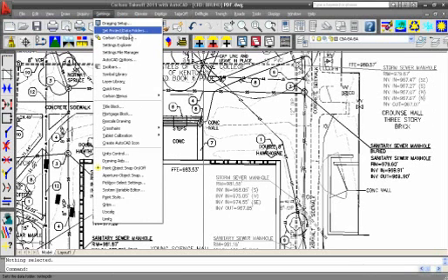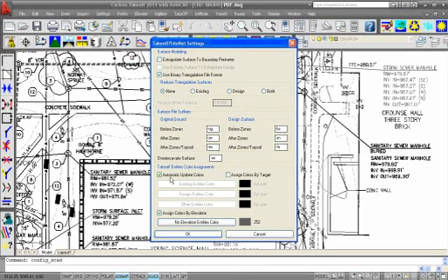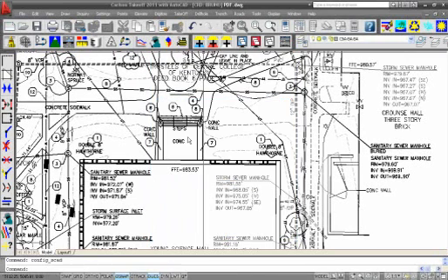and that is under Carlson Configure, Takeoff, SiteNet settings. We have an option here to automatically update the colors for the entities and assign them gray so that you can see what's elevated and what's not elevated. I'm going to check off that option because I'm working with gray line work here. So let me say okay to that.